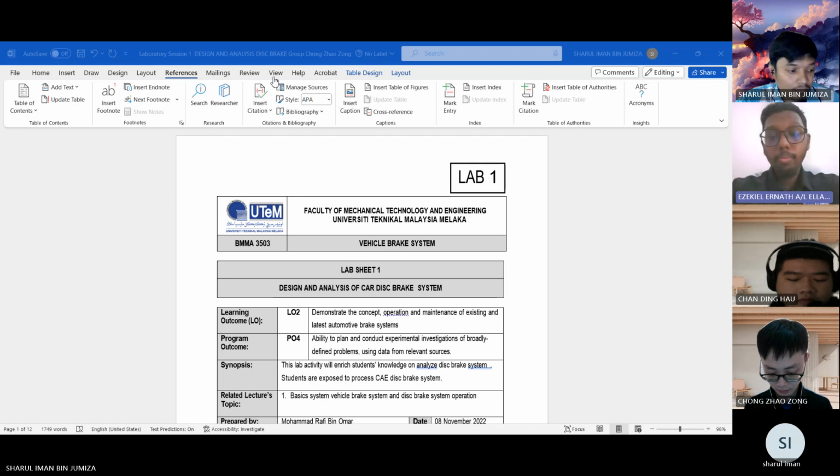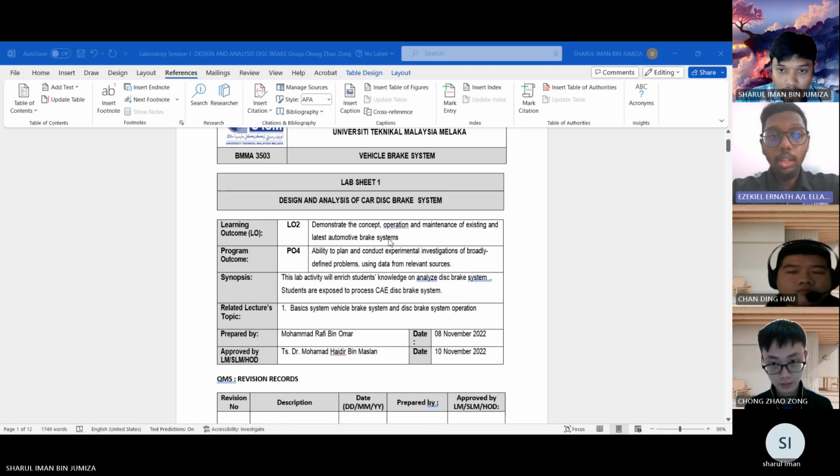And now I would like to present the basic functions of a rotor and what it is made of. The disc brake has a metal disc or rotor instead of a drum. It uses a pair of flat lined shoes or pads that are forced against the rotating disc to produce braking. The pads are held in a caliper that straddles the disc. The caliper has one or more pistons with a seal and dust boot for each. During braking, hydraulic pressure behind each piston pushes it outward. This forces the pad into contact with the disc. The resulting frictional contact slows and stops the disc and wheel.